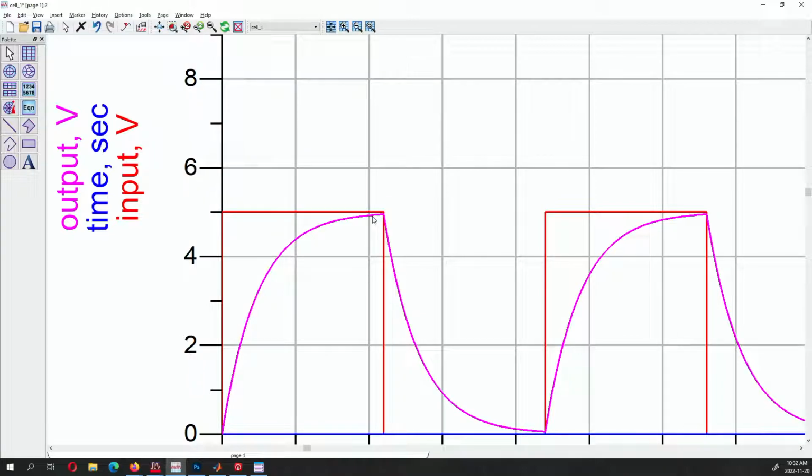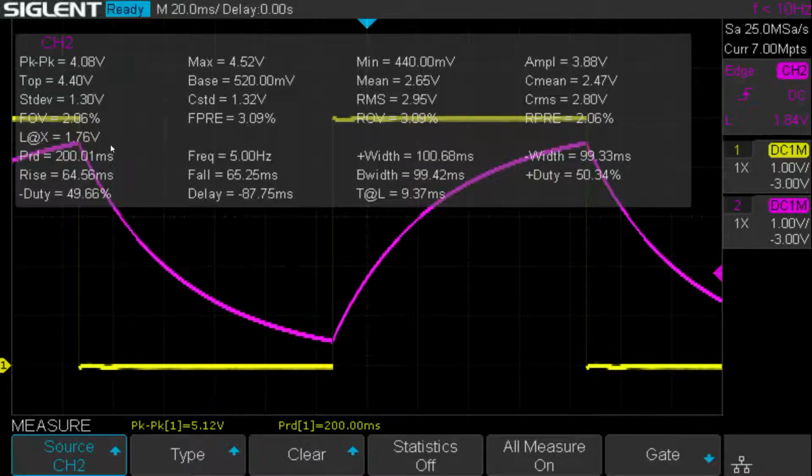If I put this over here and it's charging, by this time it should be around 4.49, whereas in real life, this capacitor, which I bought as a very cheap capacitor, probably is not the perfect 47 microfarad capacitance. It might be a little bit more than 47 microfarad, and you can see that it's not charging to its full capacity.